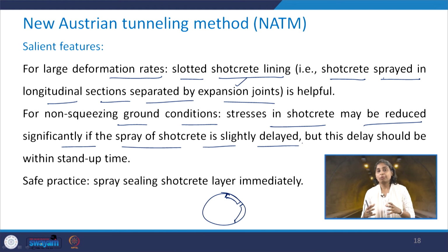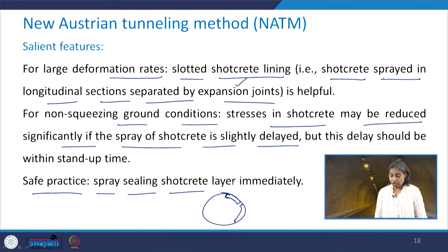Some radial deformation takes place, and therefore the release of the stresses also takes place, and hence the load on the shotcrete is going to be a little less. So, it is the safe practice that we spray the sealing shotcrete layer immediately upon the excavation, and the support system shotcrete a little later.